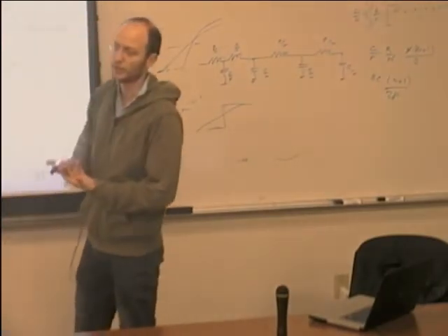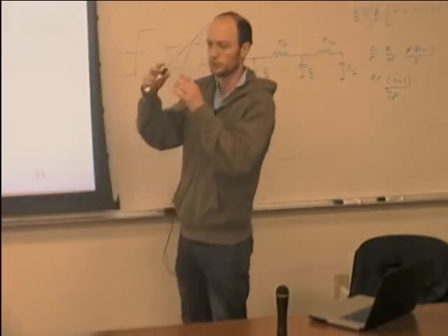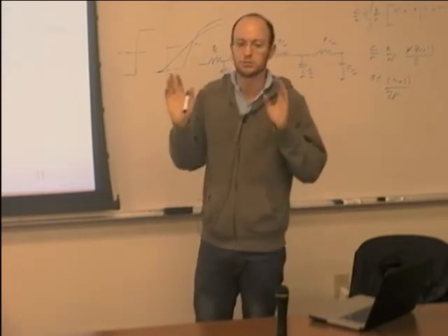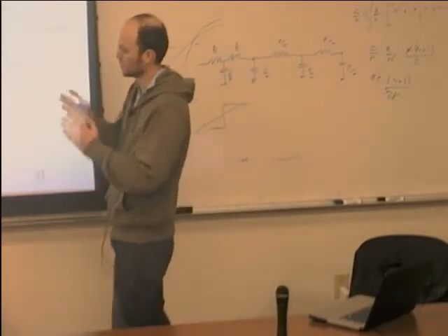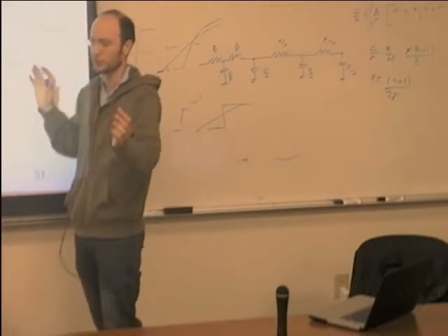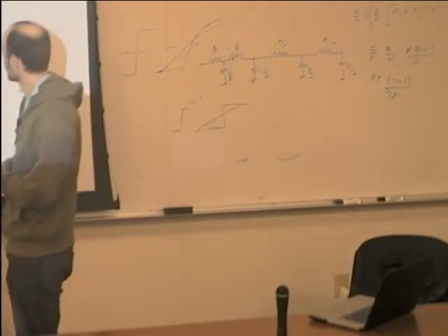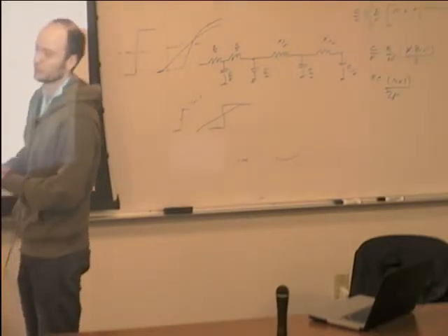And another way is that you make many gates, each of which has 2 or 3 inputs. Of course, as you make smaller gates, you get more stages. You make a bigger gate, fewer stages. So the question is really, what's the optimal number of stages?